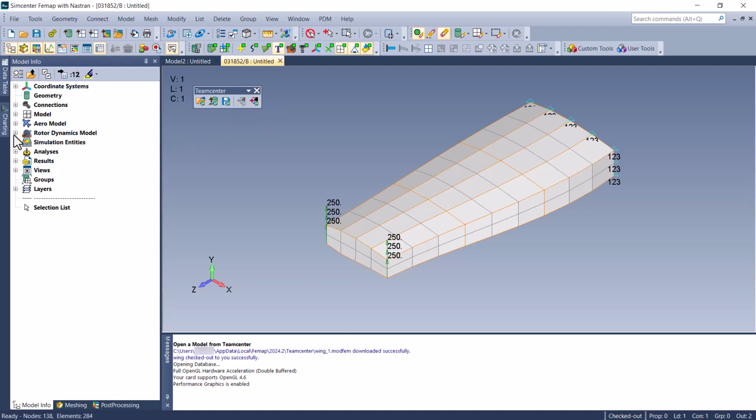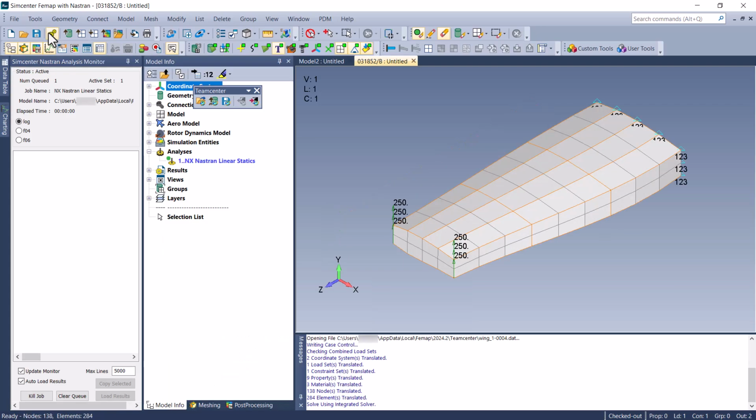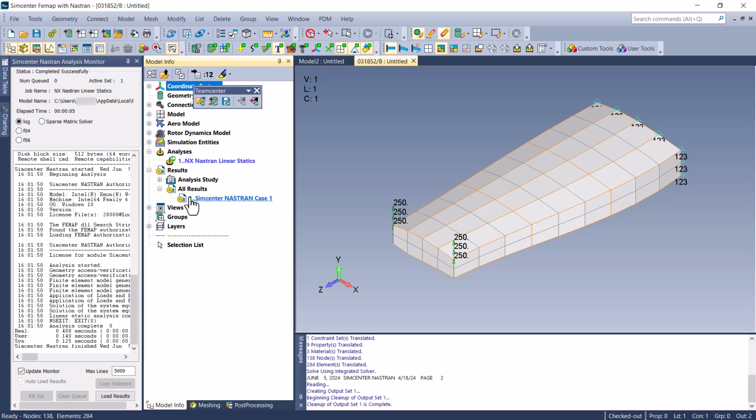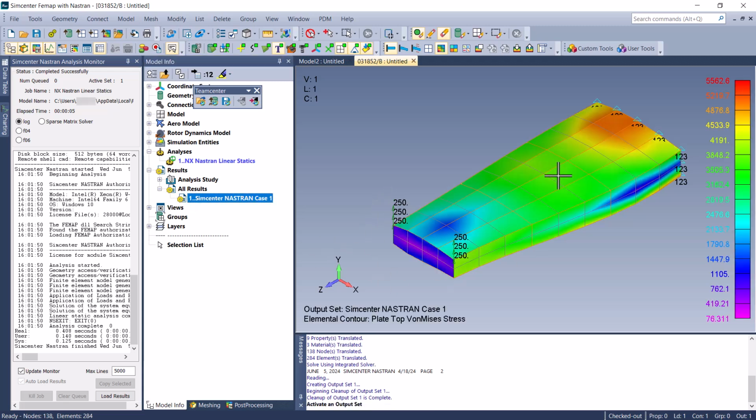Let's analyze the model and save the stress distribution on the model. Post making changes to the model, click on Check-in to update the model on Teamcenter. Check-in ensures that the current model in Simcenter FEMAP is uploaded to Teamcenter, and the exclusive lock to the data on Teamcenter is released subsequently. When working in a team, effective use of checkout and check-in helps ensure that we are not corrupting or stepping over the data, and our data remains safe and secure.